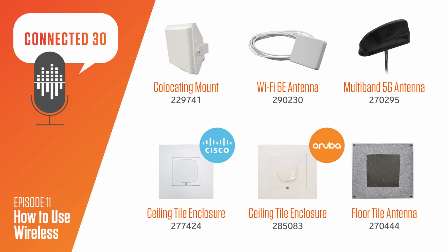So now we have a design where we can use 6E with internal antennas and place that under the flooring and still be able to transmit and receive through the floor tile. Now, one thing about these windows, they're set up in a 3x3 square design, where the windows are 3 inches by 3 inches in size. And so there's a total of nine windows, each of them 3x3 inches, on the bottom side of the raised floor. So talk about future proofing.